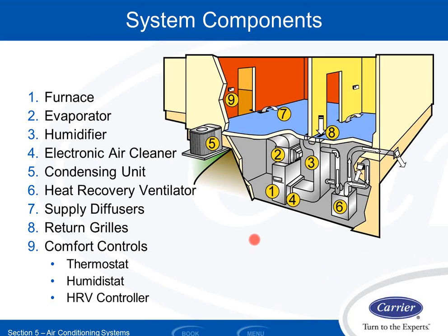Now in a lot of cases we will slightly pressurize buildings. That way we have some slight exfiltration through the building envelope instead of infiltration, but it's a very small percent. So in my example, if I put 100 CFM into a room, I probably need to be able to get 90 CFM back out of the room through the return duct system. If you have rooms that don't have a return duct, it's going to be very hard to condition those rooms unless you leave the room's doors open, which in most cases, like a bedroom, you don't want to do.